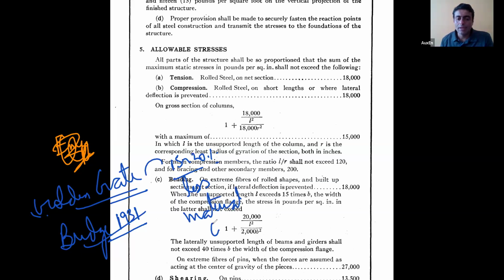If you were to design and build the same structure today, probably you could achieve 15 to 20% less material consumption, not composition, consumption. The main reason is the improved manufacturing processes and our improved understanding of material behavior. Because of our increased confidence, we allow more stress levels on our section.